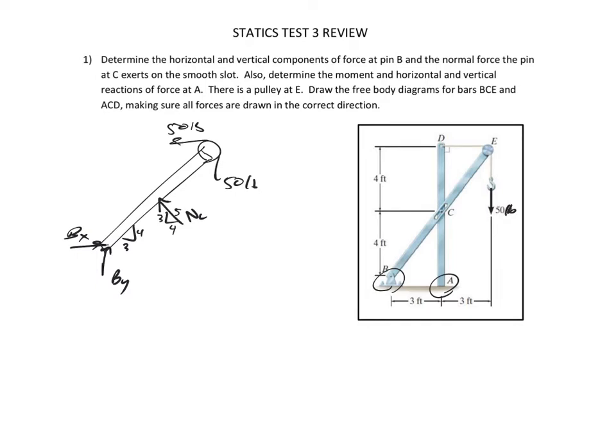If I ask for the free body diagram, like I'm doing right now, I want you to include the axes, whatever you're going to call X and Y. Maybe I shouldn't write those right down. I need to figure out what axes I want to use for my X and Y. And then this would end up being, if it's a 3, 4, 5, this would be 5 feet, 5 feet, right there. All right, so I lucked out in that I had only 3 unknowns for that free body diagram, and I have 3 equilibrium equations, so I can solve.